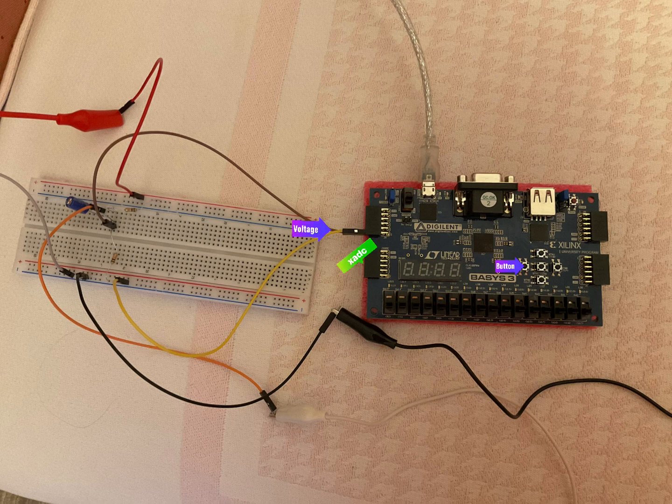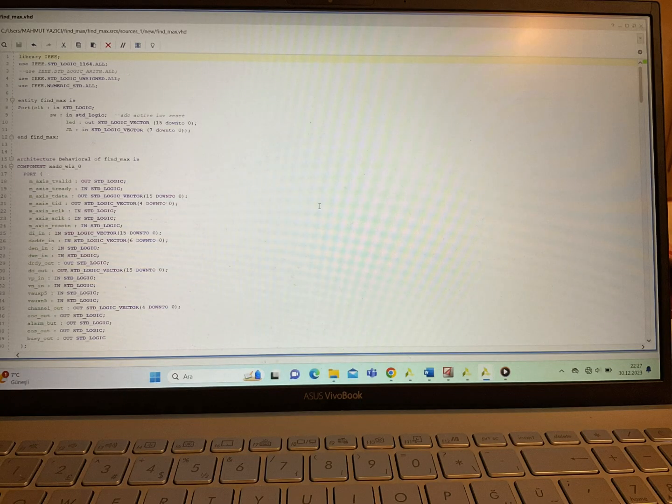So the analog sound signal coming in is converted to digital by the XADC in the Basys 3. After that, the output of the ADC is given to the FFT IP. By analyzing the output of the FFT, frequency and corresponding magnitude of the complex output are calculated, which are then used to find the most played note. Also, the button is the reset input for the XADC, and we should press the button once for the code to start working. Now let's trace the code together a bit.